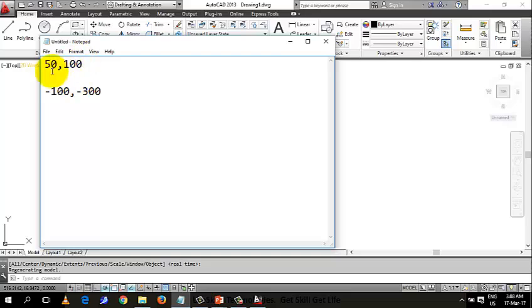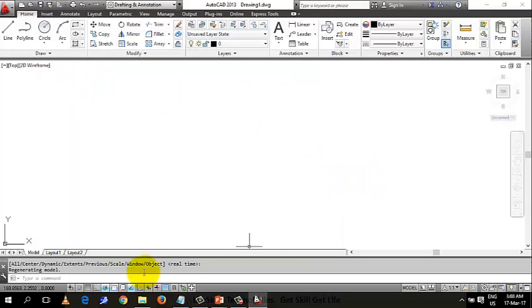That is, I know the coordinates of all the points on my drawing. So it's a line. I have the first point, I have the second point. So I start the line command. Now there are many ways to start the line command, but let's start by clicking line here. Okay, AutoCAD says specify the first point. You have to be looking at the command window. It's very important that you look at the command window here. Look at my mouse. The command window says you have picked the line command. That's the meaning of that. AutoCAD now says specify the first point.